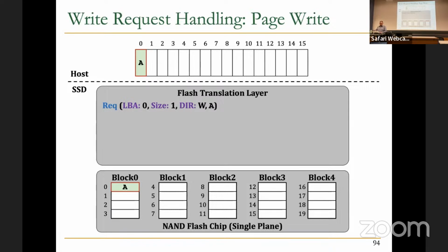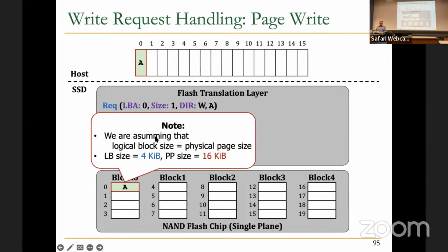So in the hardware, in the SSD backend, we write this A value in block 0 and page 0. So things are okay at this moment. Here also we are assuming that logical block size is equal to physical page size.